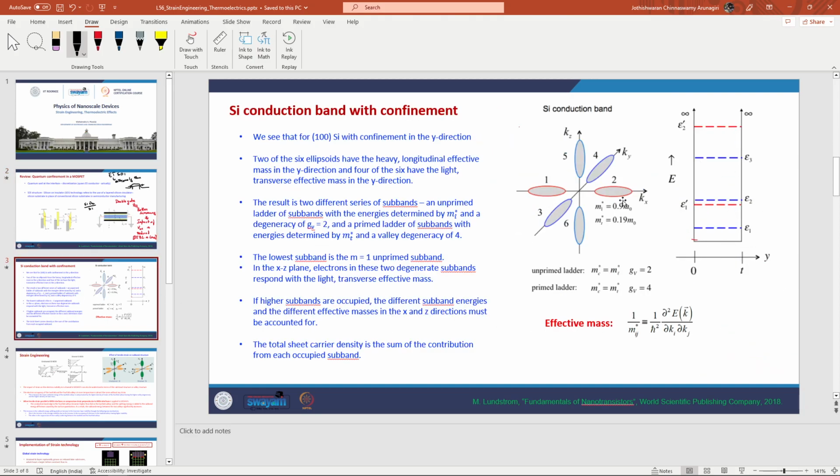However, because of strain, all these six energy levels do not behave identically, because the lattice parameters are changing in one direction. So we shall have two different sets of discrete energy levels. A rough idea of the motivation can be understood in terms of one-dimensional confinement, where we can think about the particle in a 1D well.